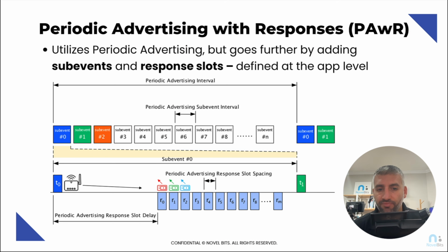So in that case, you wouldn't want to send the image data over the periodic advertising train. Instead, this scanner, this access point, is usually able to connect to each of these devices directly without having to scan for the device advertising and all that. It leverages the PAwR system to establish a connection, transfer some data, and then disconnect and go back to the PAwR work.